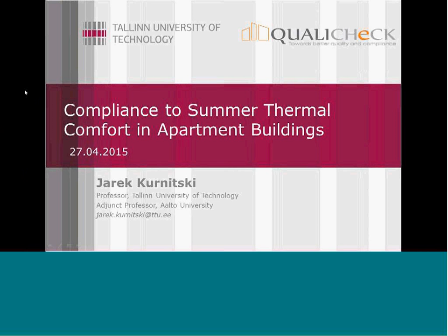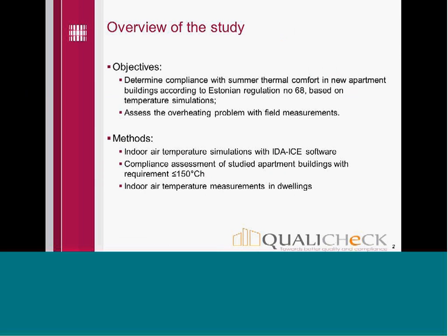Well, now you should see my slides, and my presentation is about overheating in modern apartment buildings in Estonia. This study assessed the compliance with summer thermal comfort in new apartment buildings according to Estonian regulation, which sets overheating requirements based on the temperature simulations which need to be run as a part of EPC calculation.